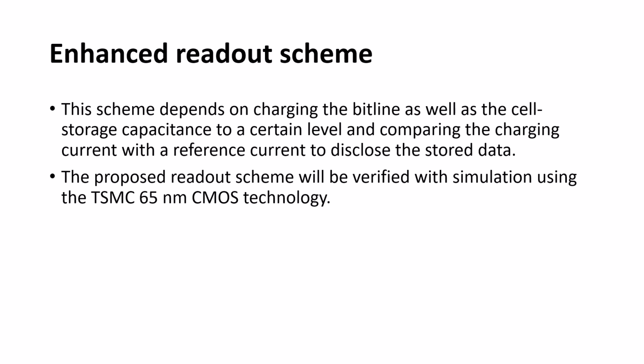Next, coming on the other hand, the enhanced readout scheme. So what this enhanced readout scheme basically employs is that if the bitline as well as the cell storage capacitance is charged to a certain level, then the charging current in case of one storage will be smaller than that in case of zero storage.